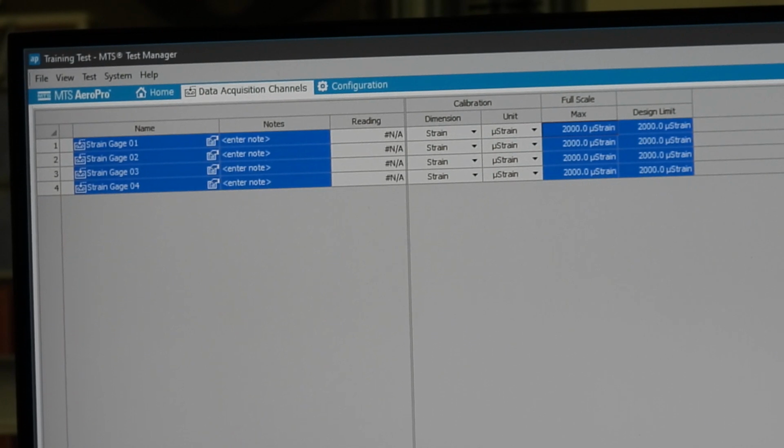The conditioner gain is solely based on, I think, in terms of the internal conditioning here, the gauge factor and your excitation voltage. This one, the max was like plus or minus 5,000 microstrain, and if it ever went above that, it would just on the data file say 5,000.